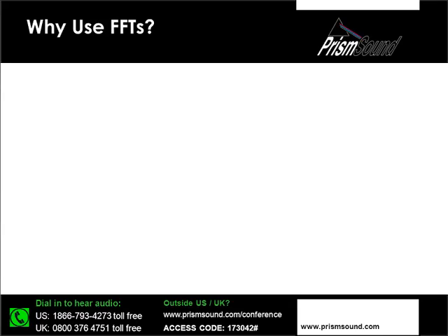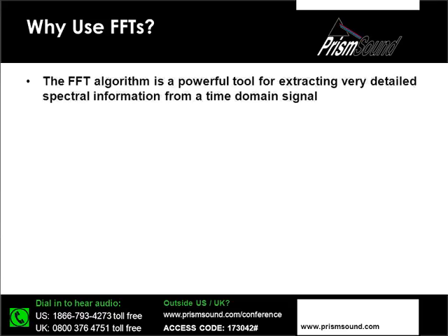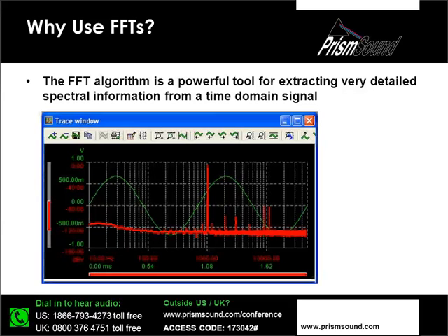Okay, so that brings us hopefully up to speed on what the FFT is and what it does. Why do we use them? Well, the spectrum is actually potentially very useful to us. The FFT algorithm is very powerful and allows us to reveal minute low-level detail in the spectrum of a signal that isn't visible in the time domain waveform. All we can really see in this example here, in the green trace, is a sinusoidal signal. That's about the level of detail that we can establish from that particular